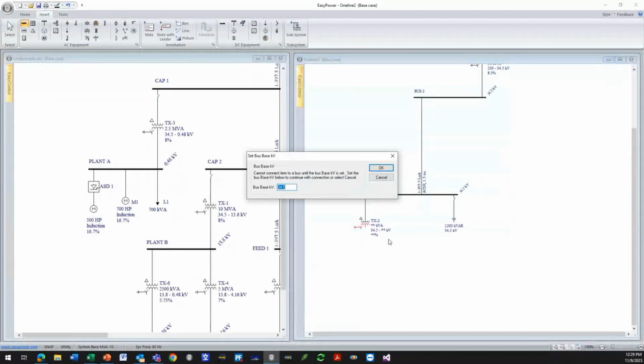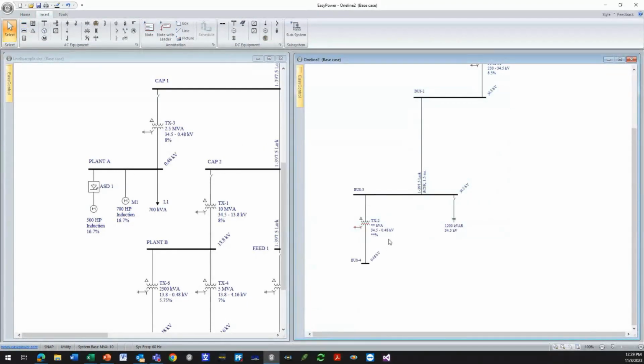As I may have noted earlier, for low voltage systems, most of my analysis is involving medium voltage networks. And so the detail of the low voltage is not as critical, but I know what parts are critical. Motors, connected motor kVA, static loads as a lumped value, both of these as lumped numbers.